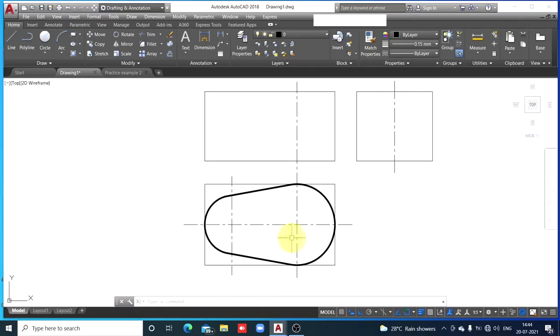Now this is a base plate. Dimensions you get in the top view are length and width vertically. So height appears in the front view and in the side view. And it is a base plate. So from the base you are going to measure a height of 20 millimeters. Identify the base, and from the base check that green rectangle there. Click it, because from the base you are going to measure 20 millimeters. You want a height of 20 millimeters. So click it upwards, move the cursor upwards, and for an exact 20 millimeter length type 20 and enter. So check here, you got height 20.